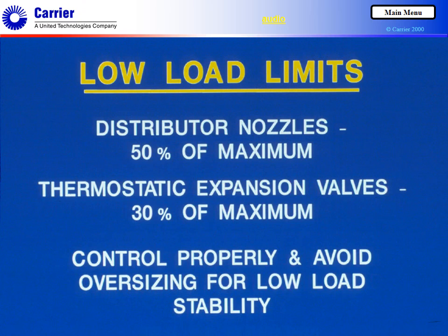If either of these devices is incorporated on packaged factory-assembled equipment, there should not be any low-load problems. This statement assumes all other components are functioning properly. However, if the nozzle or valve is selected elsewhere, it's a potential source of service trouble at low load. Oversizing either component or controlling capacity steps improperly can cause problems. Oversizing is the most common source of these problems.